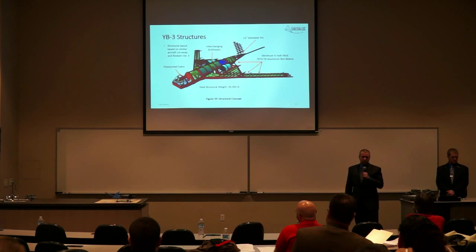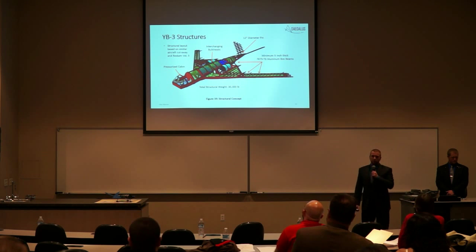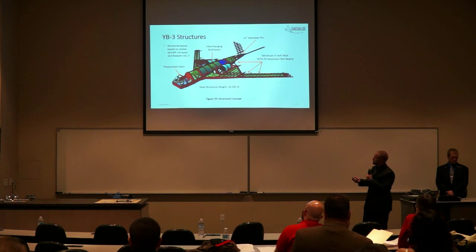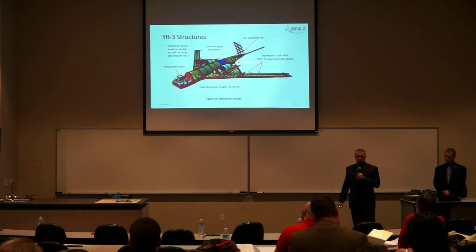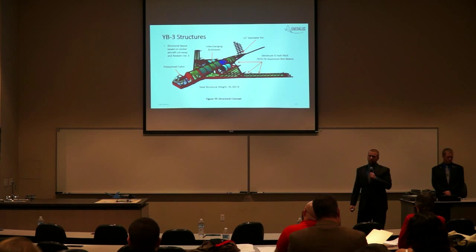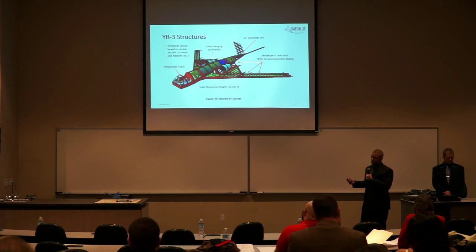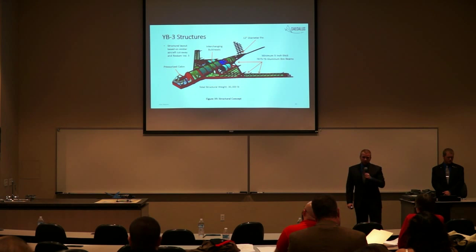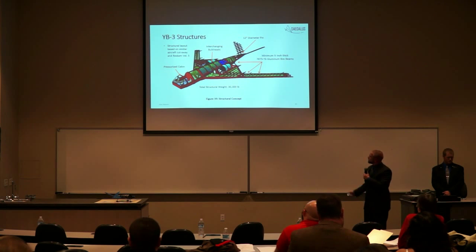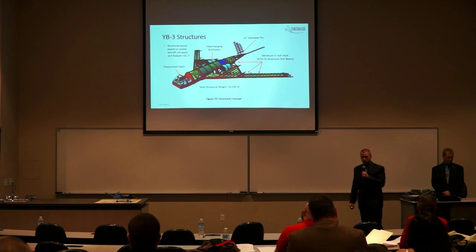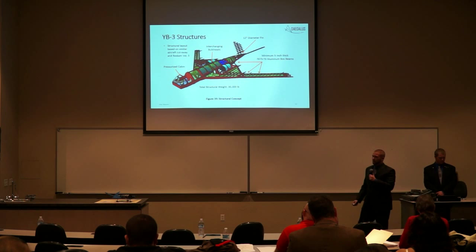As far as mission versatility goes, we have a reconfigurable bomb bay, which involves replacing and interchanging the key structural bulkheads within the bomb bay to incorporate both two 15-foot rotary launchers as well as three 10-foot rotary launchers. As a result of our all-moving tail, we have calculated a pin diameter of 12 inches. And similarly, we have a pressurized cabin that enables the crew of the aircraft to maintain steady pressures and temperatures.